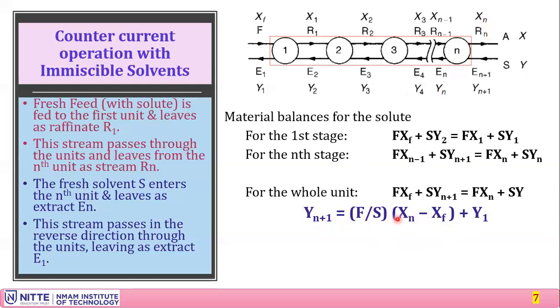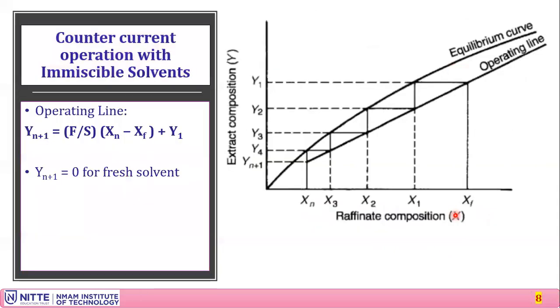So this is one straight line equation. If you see it, all x and y are of the power 1 only. So let us analyze how we solve it using the equilibrium diagram. Operating line and equilibrium diagram are both drawn. This is the equilibrium line, the upper, curved one. This is the operating line.